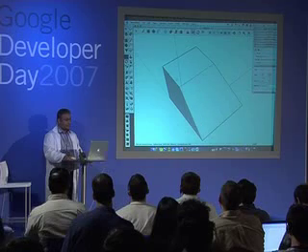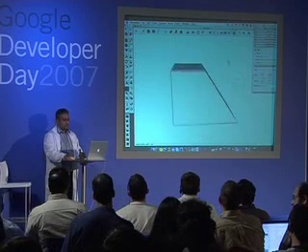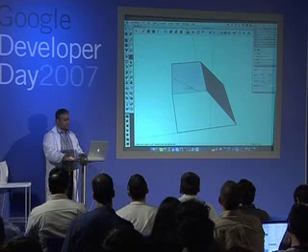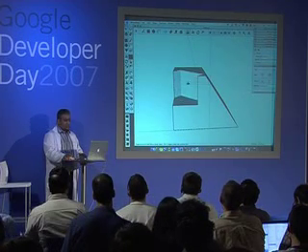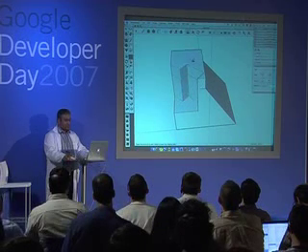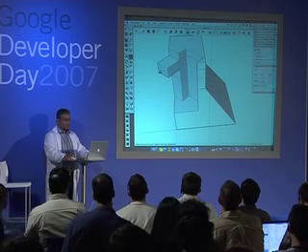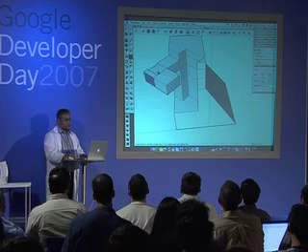Just draw on top of them. I will draw a line from there to there. And use the push-pull tool, pull it down. I can push it in, pull it out. If I use my option key, we go, and then start playing with shape.